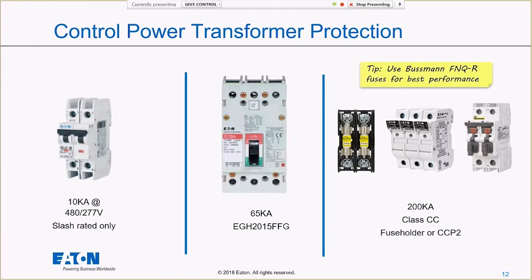Really important thing to know about this, and I know that it's always written on these devices in all caps letters, but small font, because everything is in a small font on one of these, is that this is not a load break rated switch. So really, really important, when you have a fuse holder that just has that rock out capability, that is a fuse holder. You are not supposed to be using that to break a load.